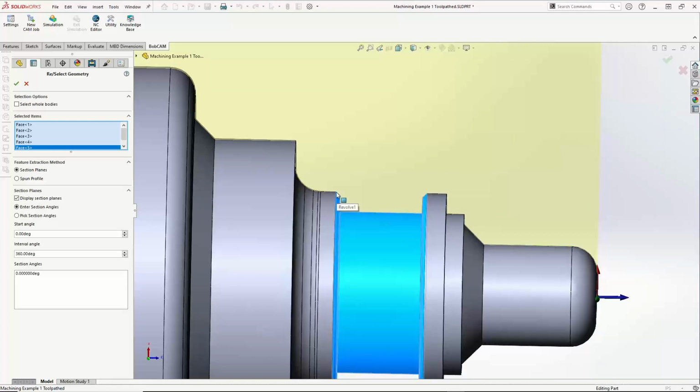And so what it's looking at is the widest point between the 2 pieces of geometry you selected and the height of them. So instead of starting the groove way out here where the stock is, because it's all gone, we're going to just have toolpath right on that groove. So we shouldn't waste a bunch of time feeding through air to get to the groove.